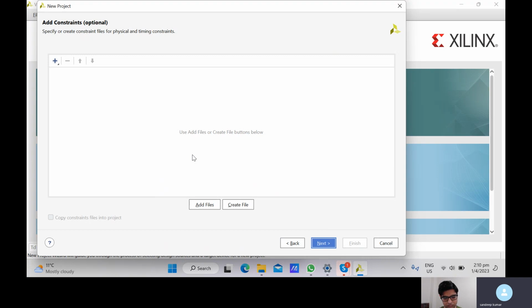There's a clock in each hardware. Based on our design, we can design hardware which can run on different frequencies, basically 500 megahertz, 800 megahertz or 100 megahertz. Design defines how you design such that you can achieve a maximum frequency. It's up to you how you design. So we have to create our own clock, or there is an inbuilt clock we can use. How does that clock work? There is usually an oscillator on the board that gives you a reference clock.